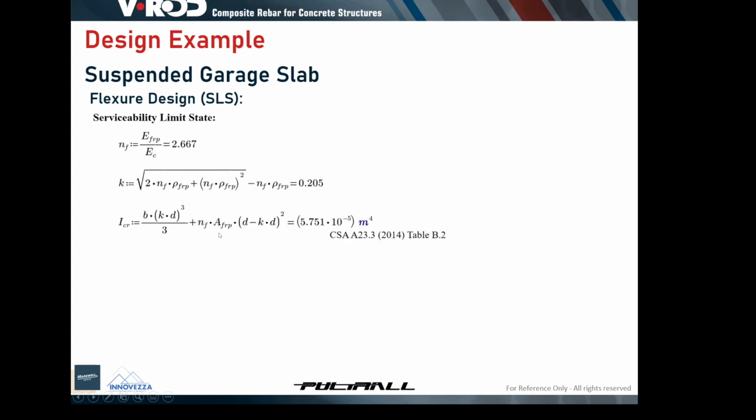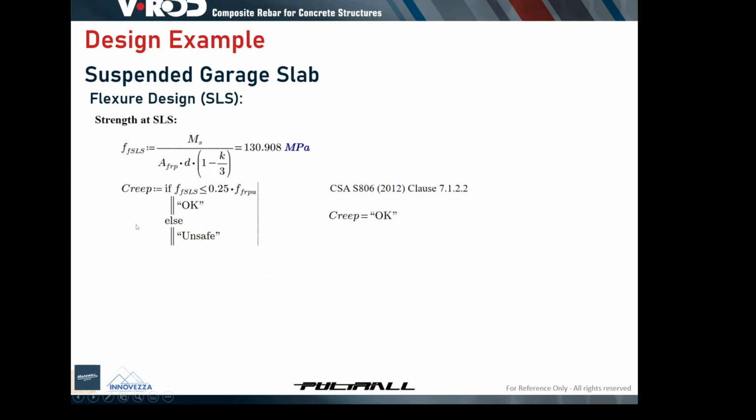For the flexural capacity at the service limit state, first we calculate the factors k and Icr. Then the stress at the service limit state, ffs, which was about 131 megapascal. This is much less than 0.25 of ff ultimate, which is 275 megapascal.